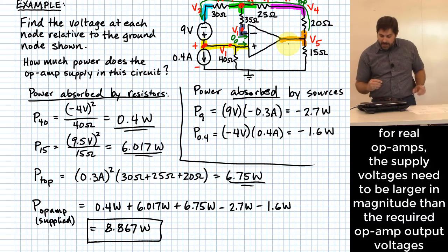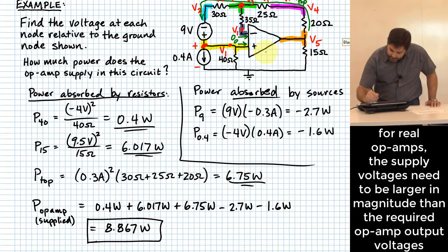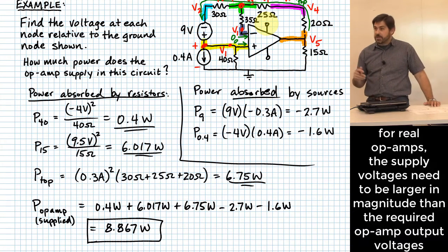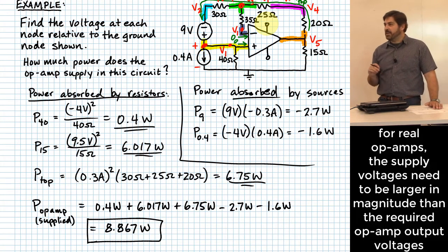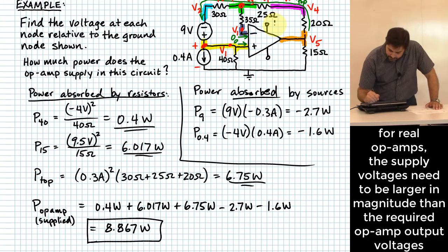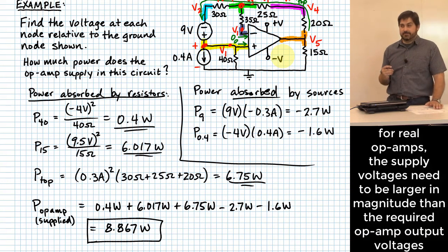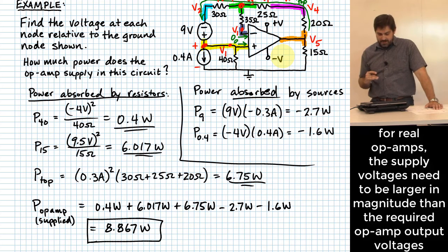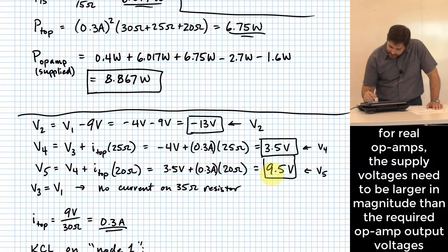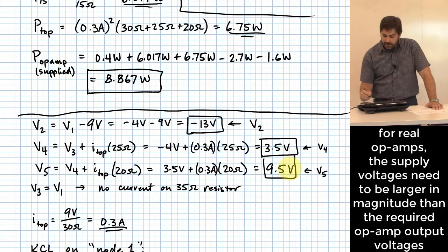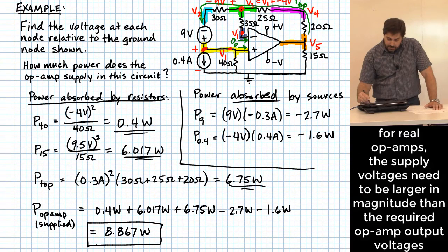The last point that I will make is that I mentioned we didn't show the rail-to-rail, or what those input rails would have to be for this op amp. Okay? Take a guess. What is the absolute minimum value that we have to have for our plus voltage or minus voltage rails? Got any guesses? Okay. We have 9 volts. It's not on here anymore, but down here we have 9.5 volts actually. We have 9.5 volts coming out of the output terminal.